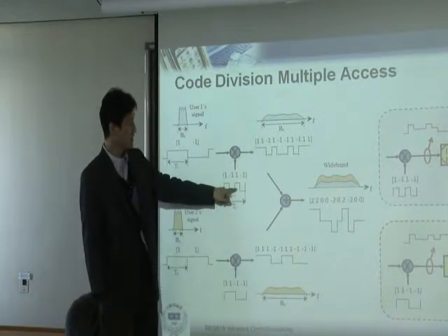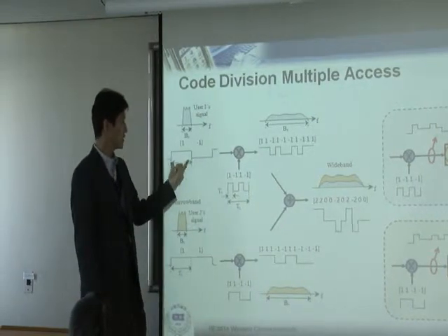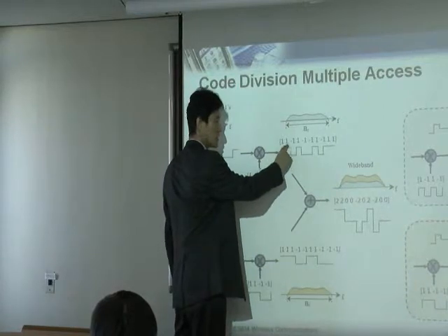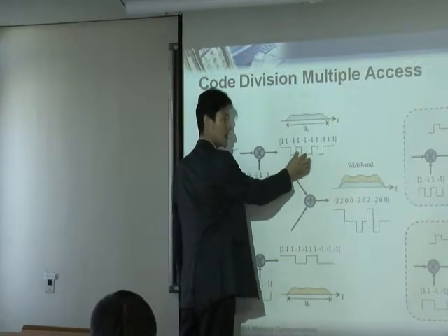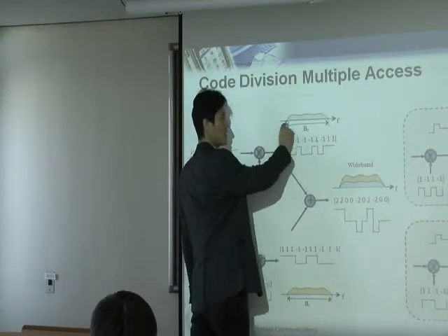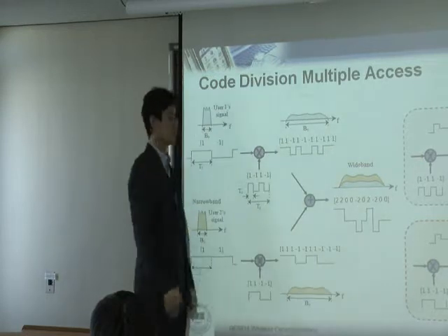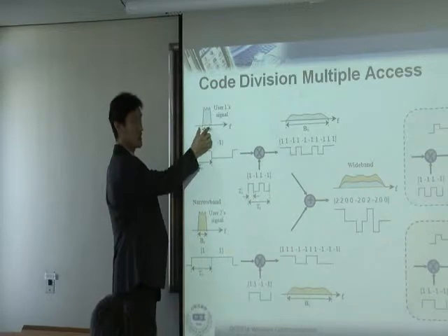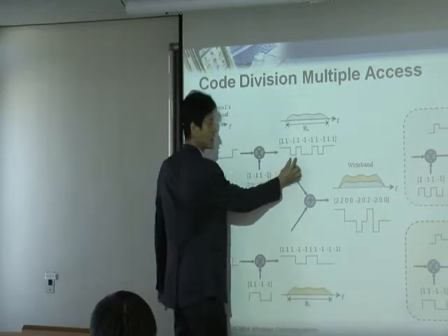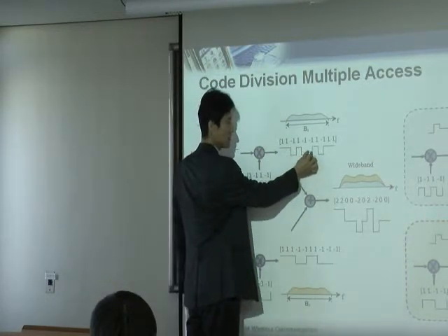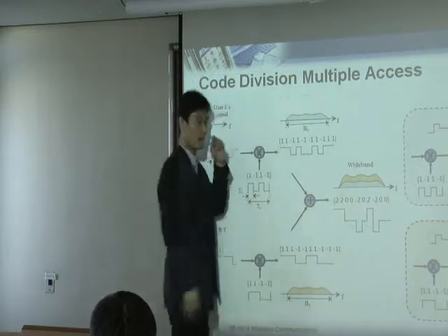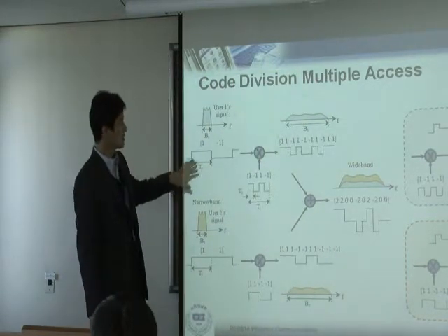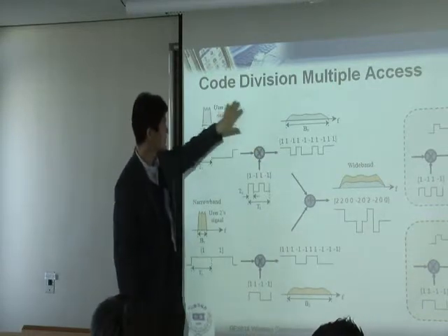Now when you multiply this chip or code, right? Everything becomes now within chip rate. So therefore, it's a fast system. It's like a spreading into the frequency domain. Because you have this symbol duration, therefore you have this narrow band, but now you have this duration for each information, therefore now bandwidth is spread. That's why we call this a spread signal. Okay? So this is time domain, this is frequency domain.